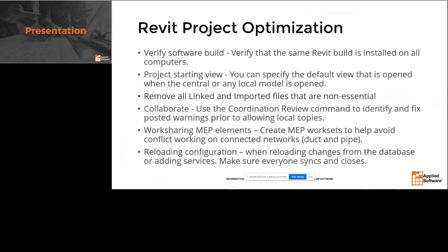Single lines or detail lines like that in a Revit model are pretty much going to bog it down. Any kind of exploded CAD file in the Revit world is going to be really detrimental to that project. So be very careful with AutoCAD, and that's one of the biggest things that we find in our models today via support: exploded CAD files can cause massive impacts on performance.